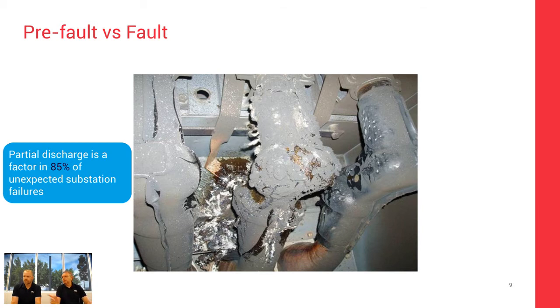Just had a few comments here. Okay. How much cheaper is it to fix before failure? And then Andrew's commented, repair before failure cost is typically orders of magnitude. Okay, so the sort of failure, we would typically look at that for, even for a cable, if you can take a cable out of service before it fails, we work that as being usually about 1/3 of the cost of letting a cable fail, and that's usually the smallest ratio.